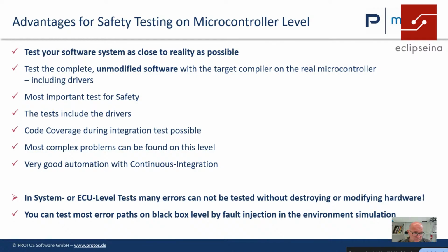The tests include the drivers. You can also run code coverage during the integration tests. That's possible. It's a bit more work than for unit tests. There are hardware solutions for that. There are software solutions for that. And by doing that, you already can see what your coverage is to spot gaps in your test strategy. It's not to verify that your test cases work. So it's not a quality proof of your system or your test cases, but it's a metric that gives you the gaps in your test strategy. Very important to do this from a certain safety level.